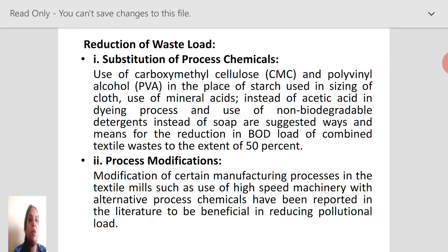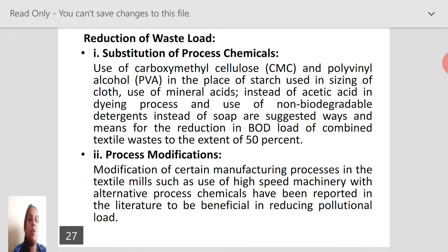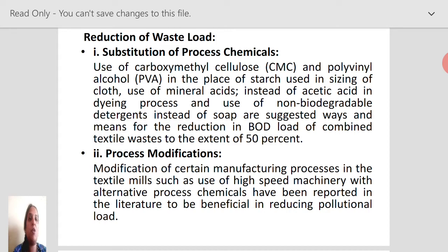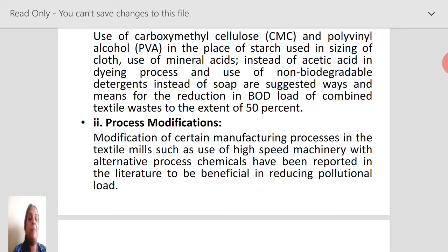That's why we already told you that instead of starch, we can use carboxymethyl cellulose as well as polyvinyl alcohol, because starch constitutes a high amount of BOD. So with carboxymethyl cellulose and polyvinyl alcohol, the BOD load will be reduced by up to 50%. It's a good amount.